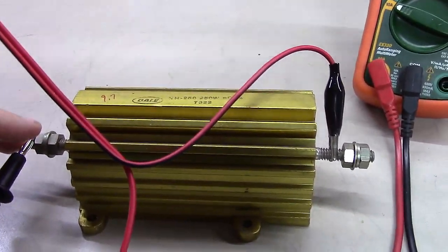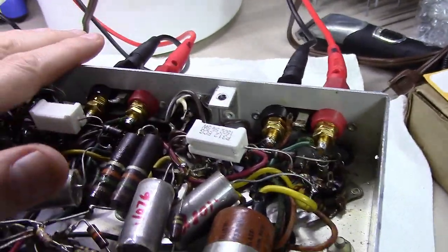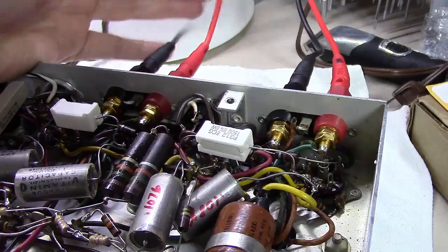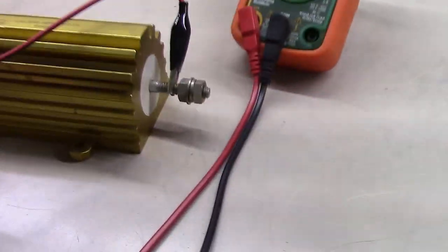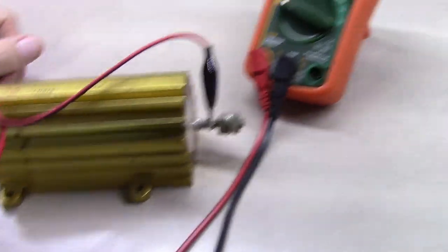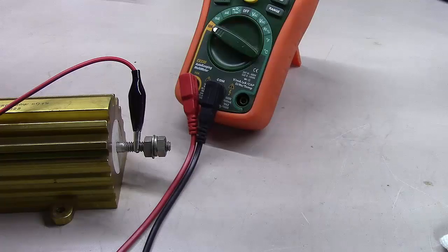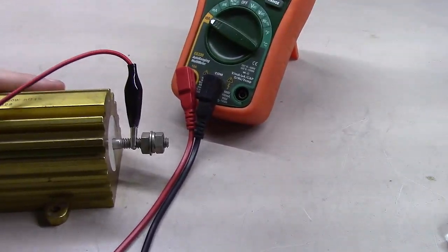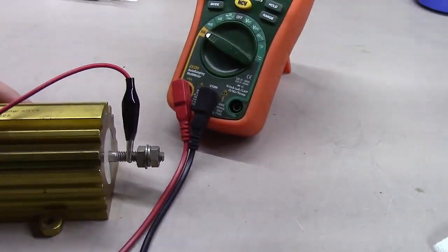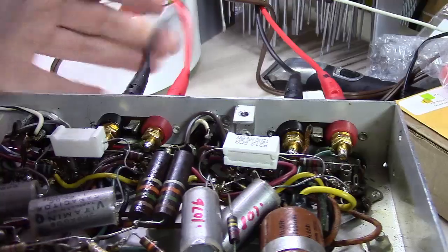I'll give you an example here. If we were playing music through this amp and feeding out of it up into the dummy load, which had one of these resistors, and let's just say that you measured 8 volts coming across an 8 ohm resistor, right? Well, then you would know that you were putting out 1 amp of current through this amplifier coming out the outside.